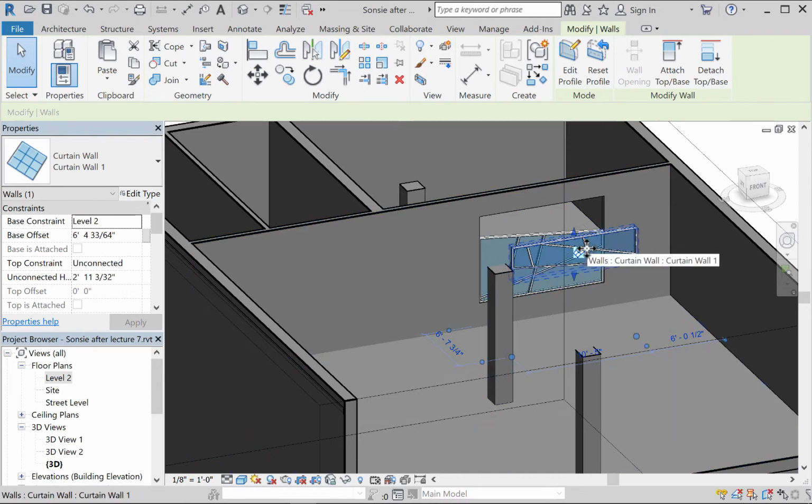There is also a final, even more complicated way that you can create an irregular shape to the window, which is to say an irregular boundary. Curtain walls don't like that. In order to do that, you're going to have basically a totally custom window, but that's way more complicated. We'll get to that when we talk about custom families. For now, leave it to be said that you can have a rectangular window in a rectangular opening using a curtain wall that can be pretty fun, but it's fairly straightforward to create.